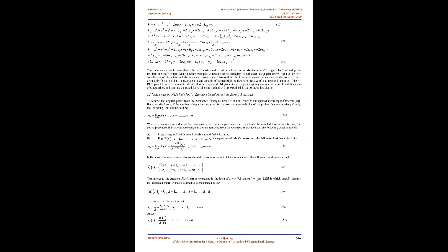Next, the algorithm used based on the resultant method will be explained parallel to the kinematic analysis of the 4RUU parallel robot. Using the joints coordinates, kinematic constraints governing the chains of each PM and the resultant method, the inverse kinematic expression is obtained for each chain of the PM. The term should be devoid of the coordinates of the inactive joints, the statuses of which are unclear. Using the inverse kinematic term obtained for each chain and reusing the resultant method, a univariate mathematical expression is obtained that explains the inverse kinematics of the PM. This univariate term includes all the answers to the parallel manipulator's inverse kinematic problem.